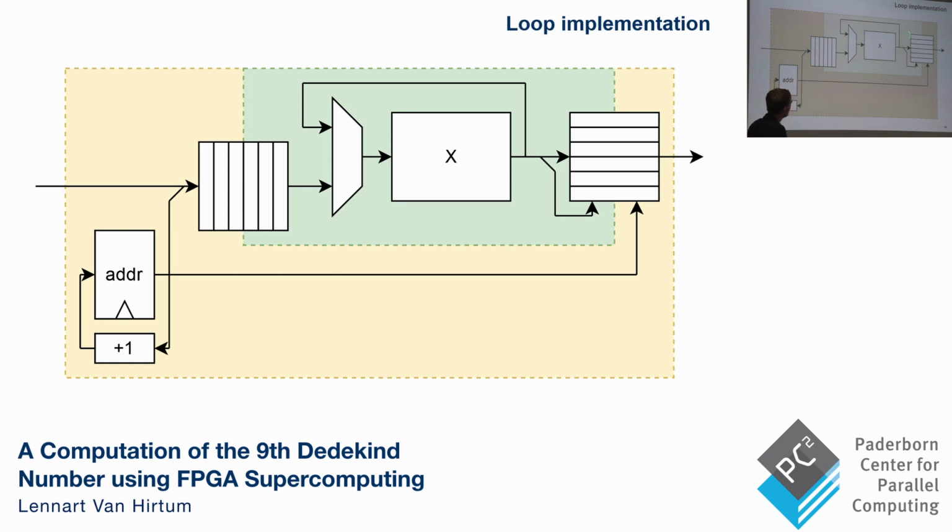When this module is ready, it'll grab one element from the FIFO, start working on it, maybe spend 6, 7 iterations working on it, and then it'll write the output for this computation to that memory location in this output memory. And what this does is the next time this address counter goes all the way up, falls back down to 0 because of overflow, and counts back up, it'll read them all out in the proper order again from the output of the memory. And so this little loop block here puts everything back in order.